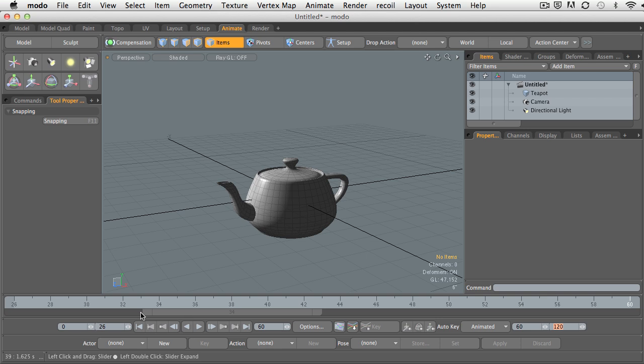Now, if we like this duration, this preview range, we can left click and drag in the center of this and drag it anywhere around in our timeline. The current start and current end values will update accordingly. This is a handy little trick. I use this all the time to jump around my timeline and to globally see how everything's working, or if I want, I can just take a look at a very small chunk. Okay, so that's the preview range values, which are on the inside.